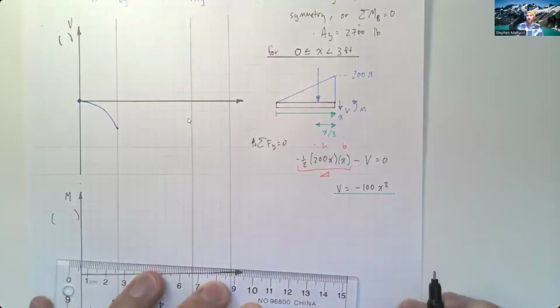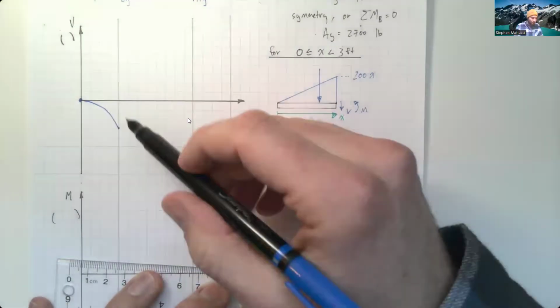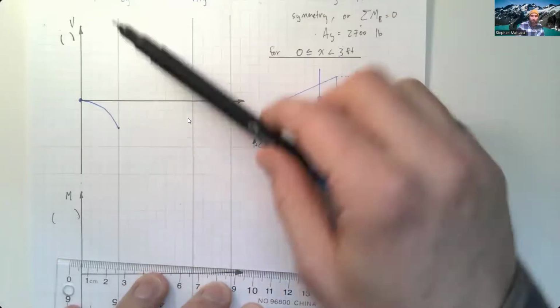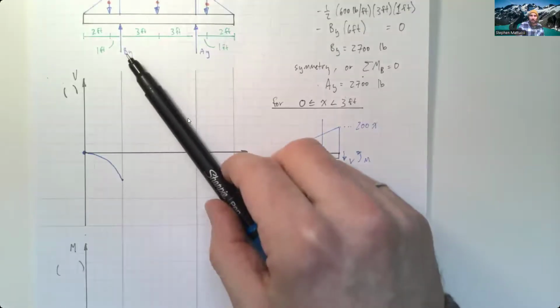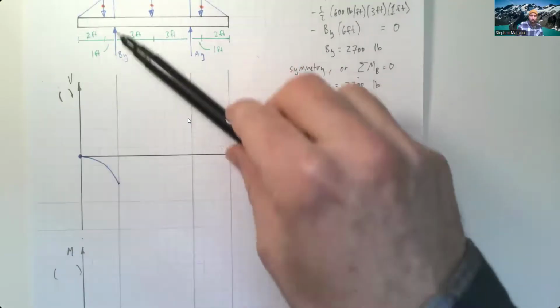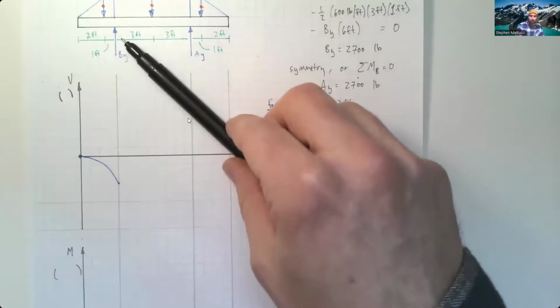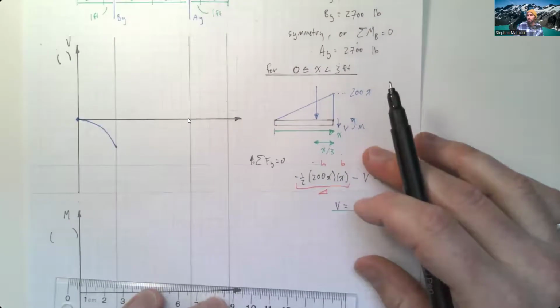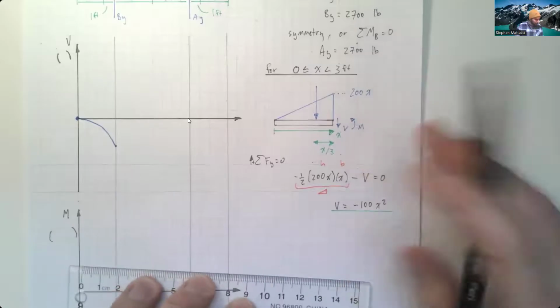Such like that. Now, at some point, I'm only drawing to this point of interest where there's going to be this point load at B. So I'm just going to leave it when we get there. And we can see ahead, if this is a point load, this is a discontinuity. So this is going to cause some kind of step in my shear force diagram.